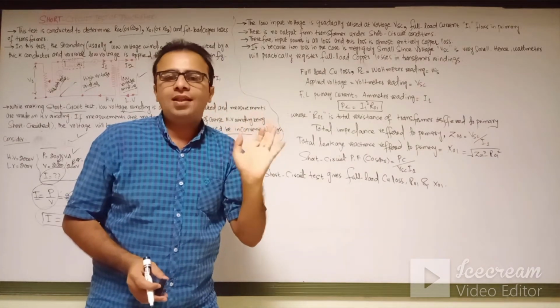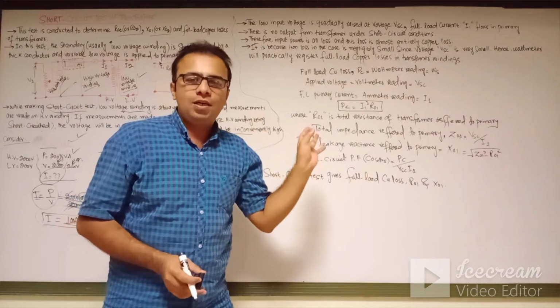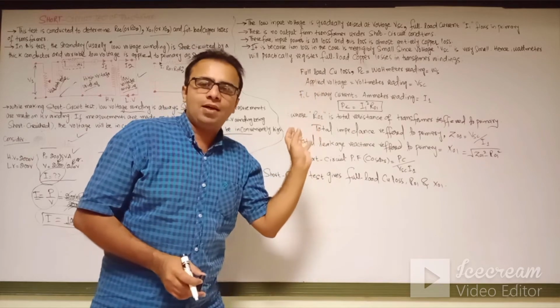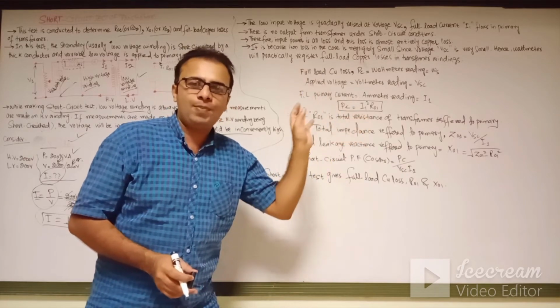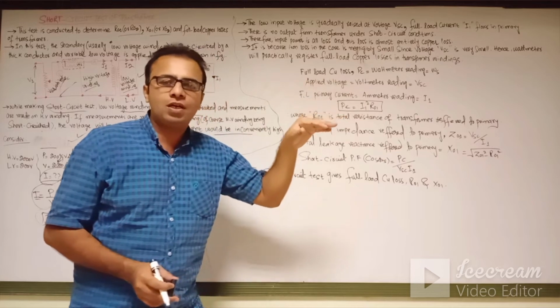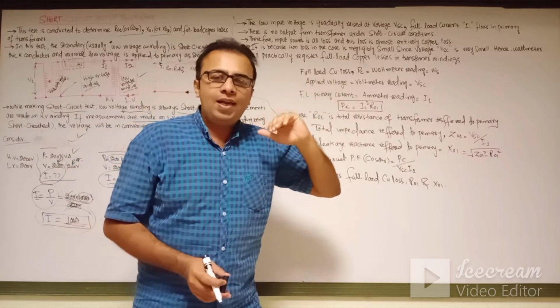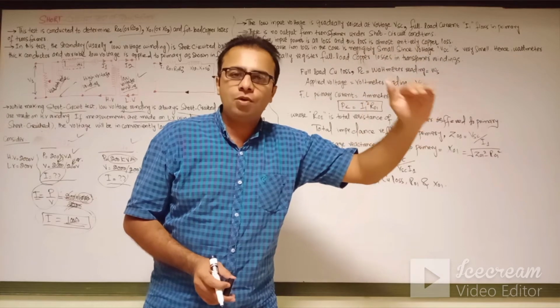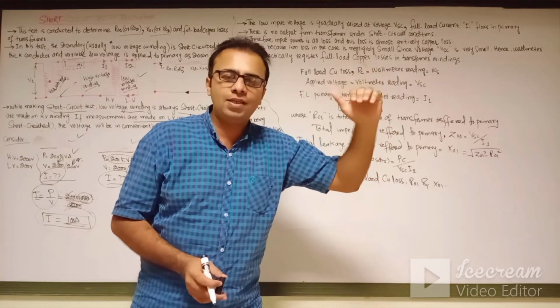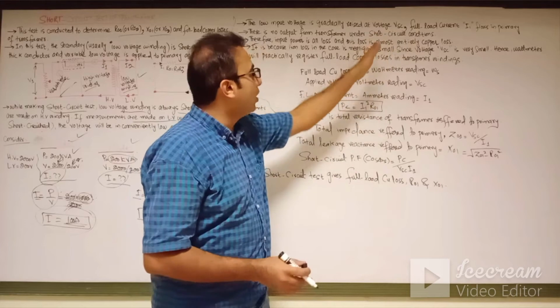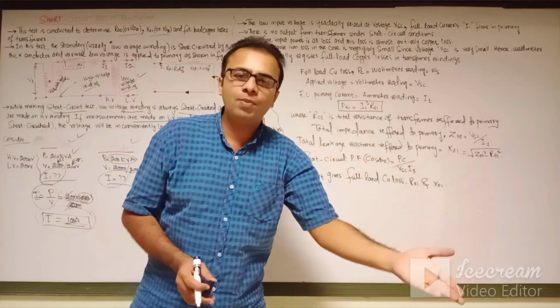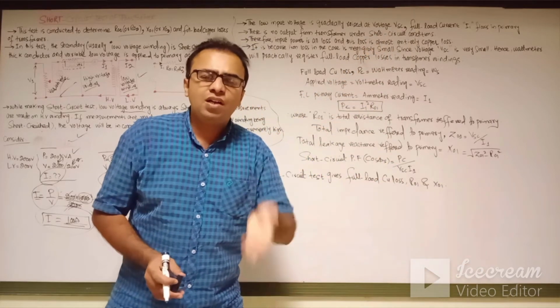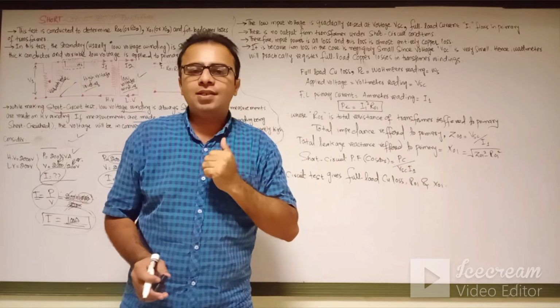That means when we give the applied AC supply voltage to the primary winding of the transformer, and V1 is gradually raised up to the VSC voltage, then full load current flows from the transformer. That full load current represents the copper losses in the transformer.